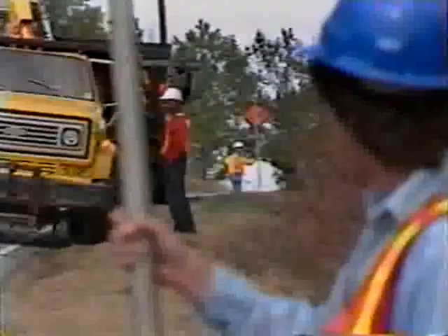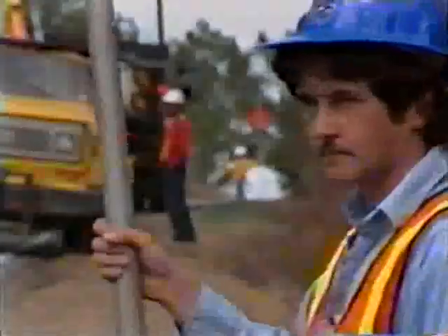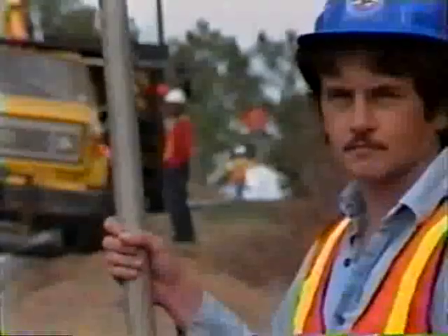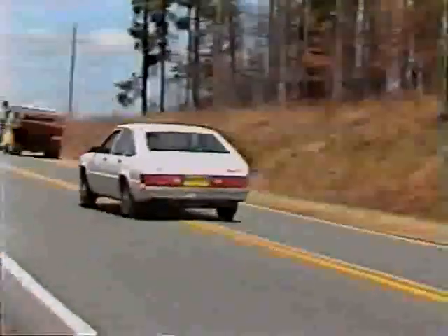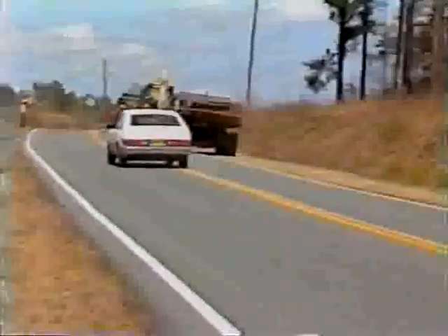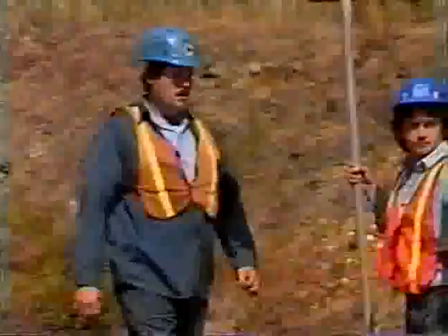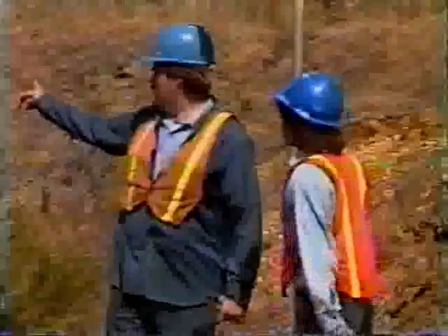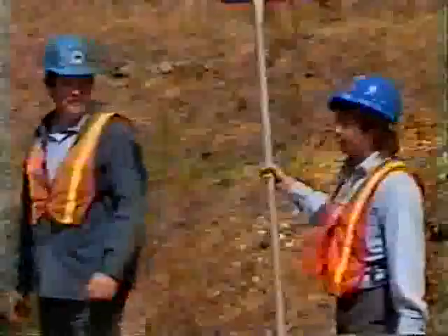It is important that the two flagmen have clear sight of each other and are in total communication when directing traffic through the work area. Do not allow traffic to proceed through the work zone until the traffic is stopped at the other end. The crew supervisor is responsible for seeing that the traffic signs are placed at the proper location and that flagmen are properly located.